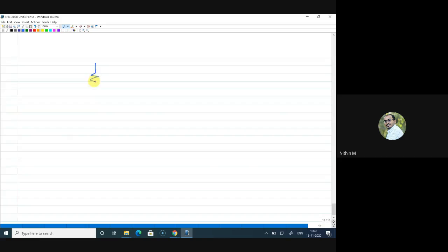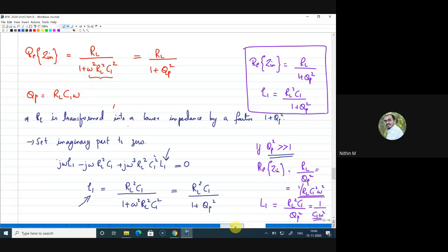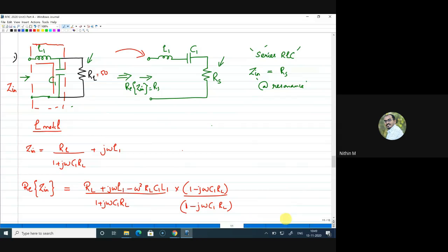Now before doing that, let me take this. I have an impedance RL here. Now the same L section I'll just place the other way. So I'll put L1 here and I'll put a capacitor here. Whatever you told, keeping C in series, is also right. I'll come to that topology as well. So this will also give you a transformation. So let me take this as case 2, and the other one as case 1.